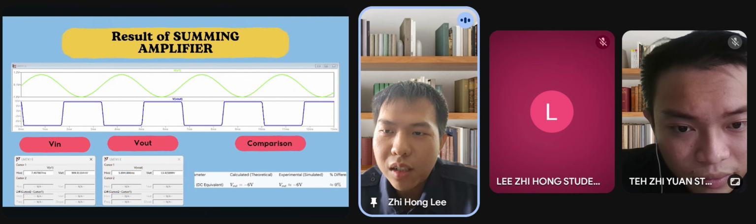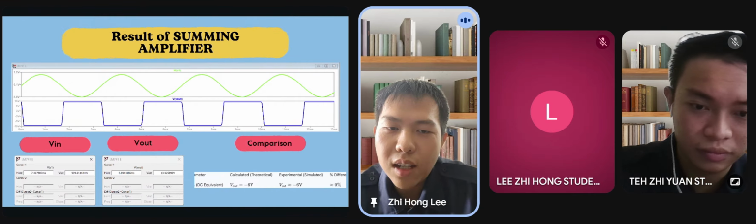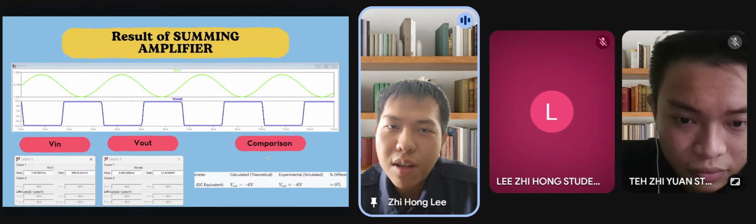However, if we significantly increase the frequency, the op-amp will face the constraint of its limited slew rate and bandwidth, leading to signal distortion or reduced gain. This represents a performance constraint inherent to the non-ideal LM741.